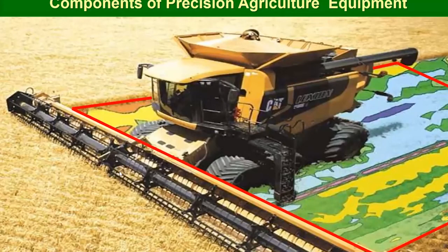So how does it work? We have the width of the combine or any harvester. I don't want to mention just combine. And you have GPS, and you are moving from point A to point B. So you have length and the width, and with these two parameters, you can calculate the area. With this area, you now calculate the mass. So you have yield per this area, meaning you can calculate it in real time.